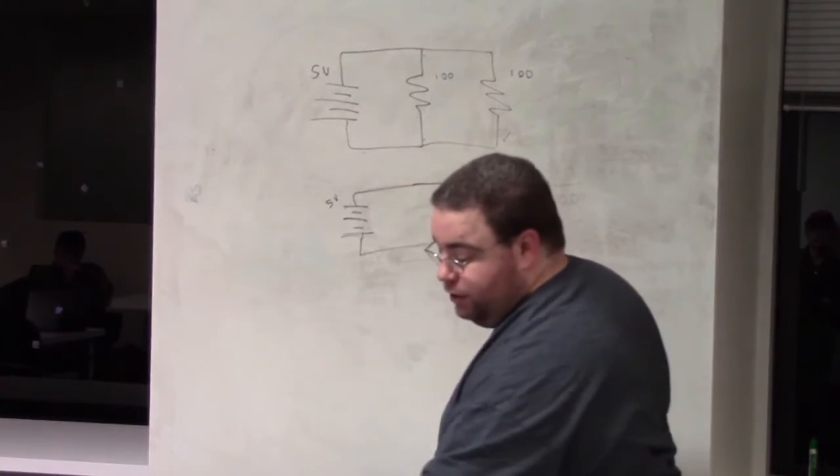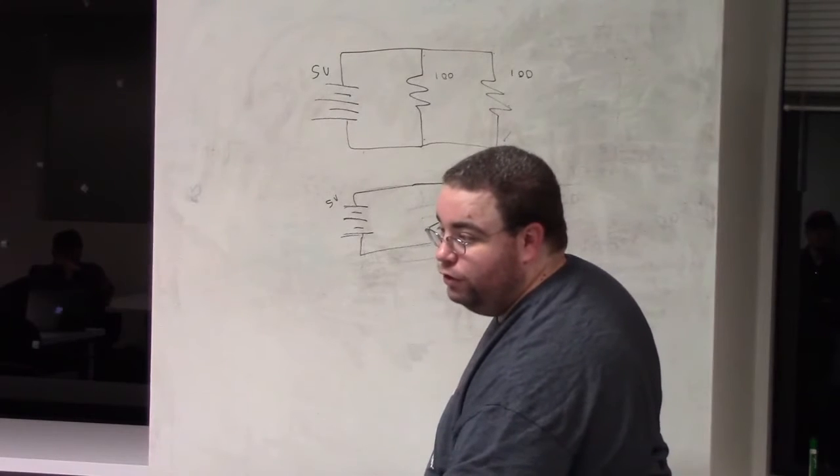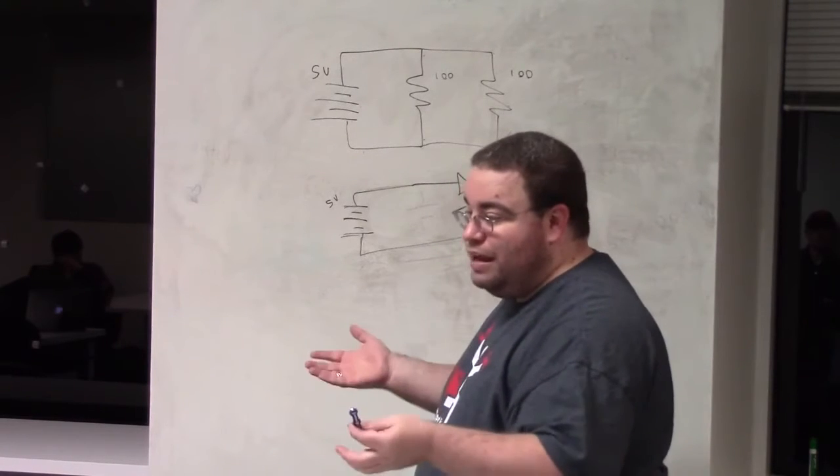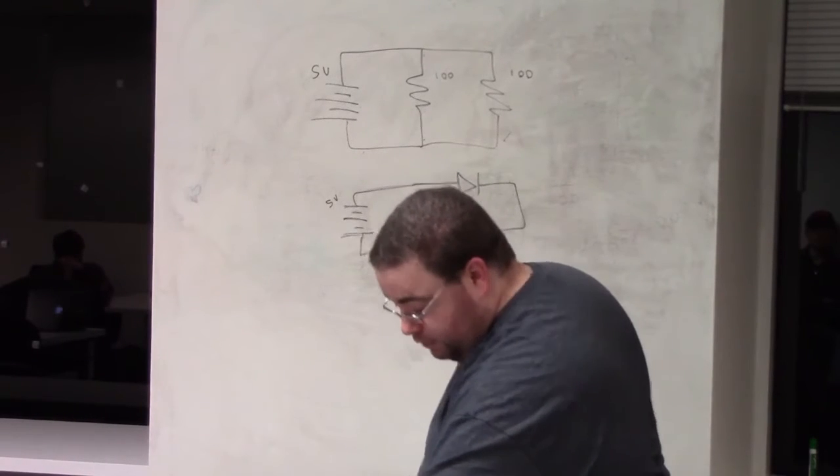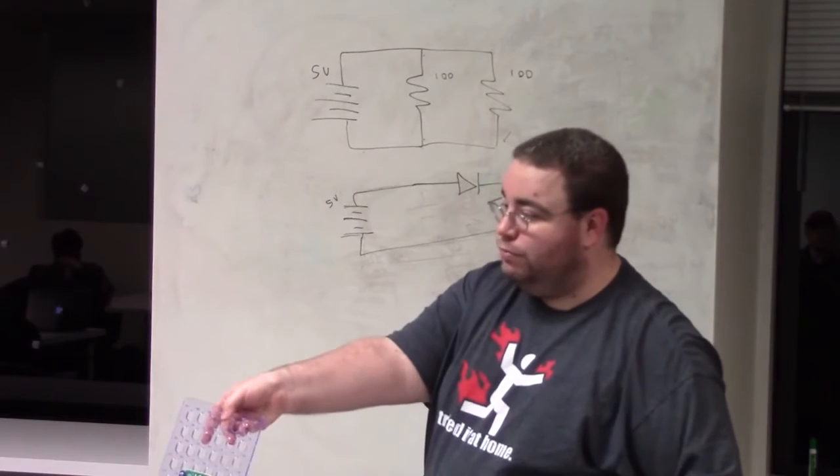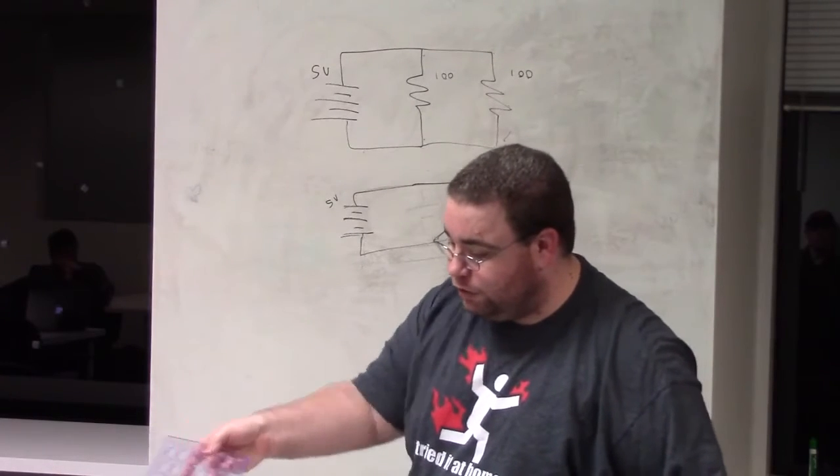Now it's going to be 4.3 volts dropped by this resistor, which we know is going to be some sane amount of current. So the LED will light up. You can barely see it because it's 100 ohm.